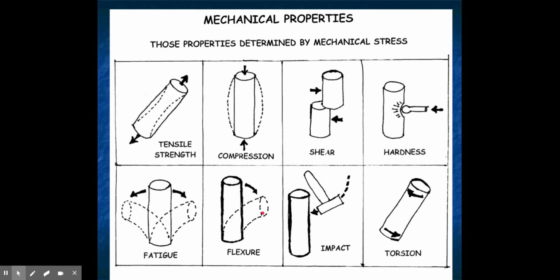A material's tendency to bend under force and its ability to bend under force without breaking. And then we go to fatigue. Fatigue is when you go bending back and forth, what's called cyclic loading. You got a load, you're letting it go. Again, loading is also stressing, or a force on it is a load. So there's many terminologies used here, but in mechanics, if you're putting a force on something or a weight on it, it's referred to as a load.